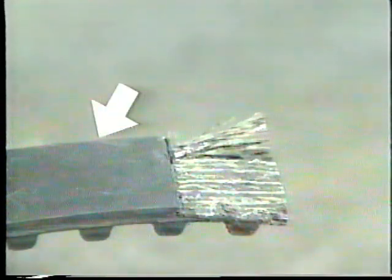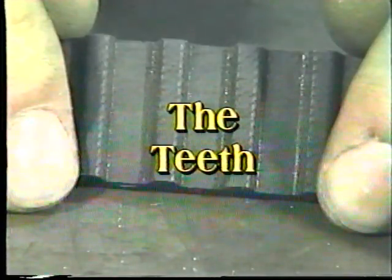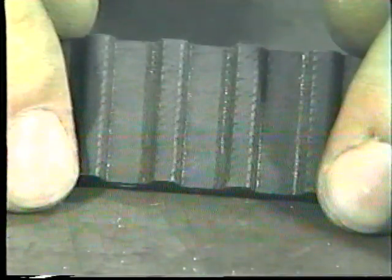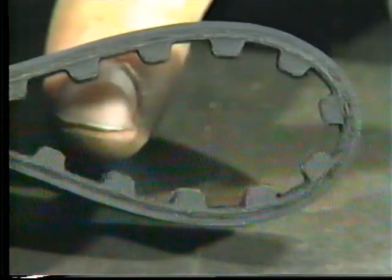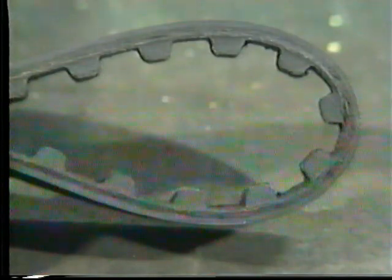It protects the tension member from grime, oil, moisture, and frictional wear. The teeth are usually made of a shear-resistant, moderately hard neoprene compound. The teeth are very strong. In fact, as long as 6 or more teeth are meshed with a sprocket, an extreme load will tear the belt apart before it strips off teeth.